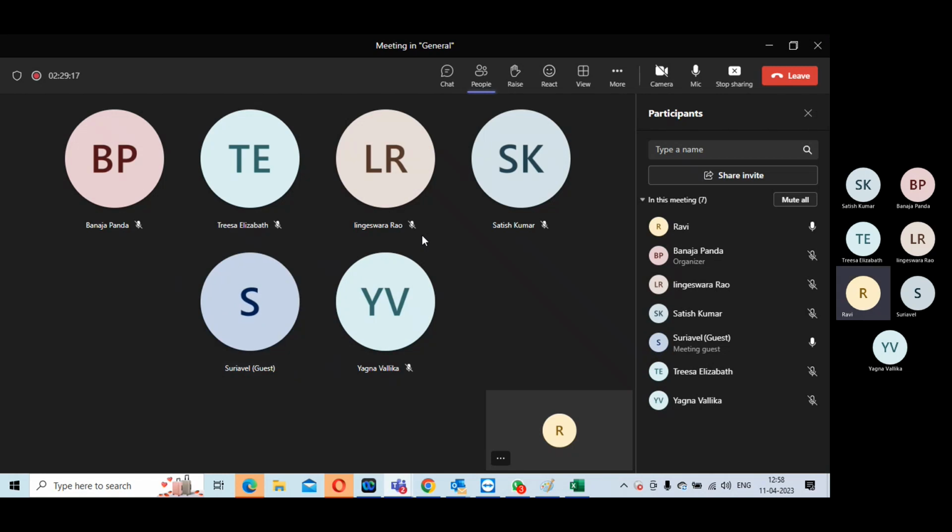When you are dealing with feed throughs, the first thing you have to look at is their fly lines. It should not be zigzag. Try to make the pins as straight as possible, input and output in a straight line, that is the shortest distance. Sometimes it will be from the left side to the bottom, then you have to align left pin to left pin, bottom pin, top pin to right. If it's zigzag, there will be a lot of crisscrossing and you will get congestion.